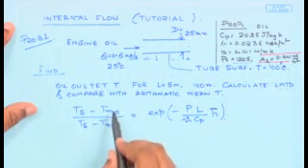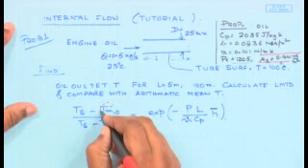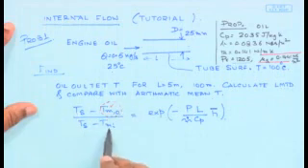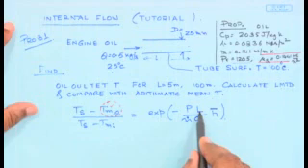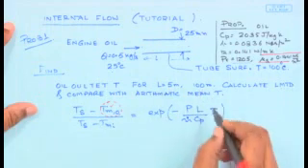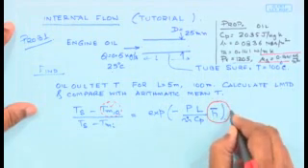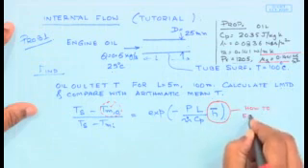So we need to find out what is the value of the mean temperature. So this is something which you would like to obtain. Ts is provided, Tmi, the parameter, the flow rate, Cp etc. are provided. The length, in one case it is 5 meter and in one case it is 100 meter. So the problem essentially boils down to how to evaluate h bar.